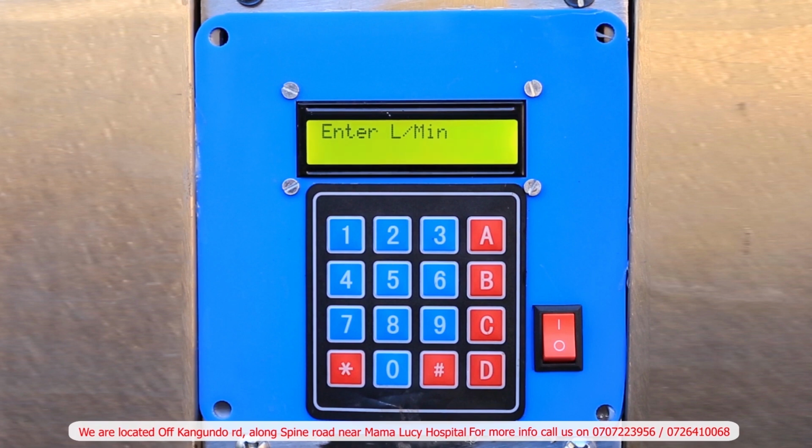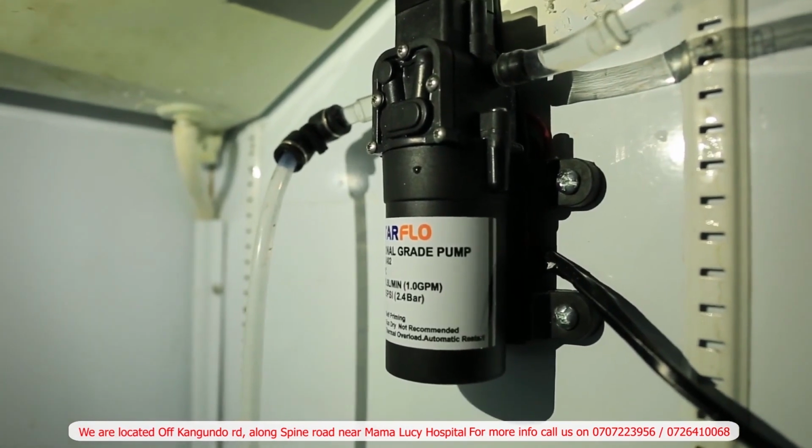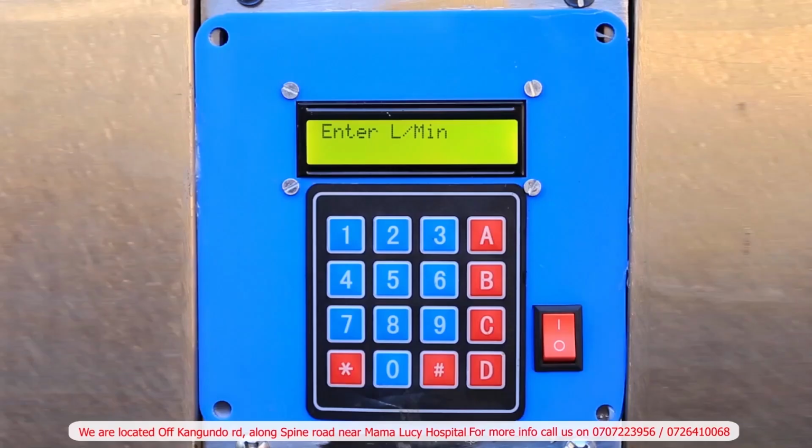To verify that, I will be required to check the value indicated on the pump when you open the door of the machine. It is indicated at 3.8 liters per minute. Therefore, I will come back to this PLC and key in 3.8. Kindly note that the star key functions as a decimal point. You can use it to key in your decimal point.